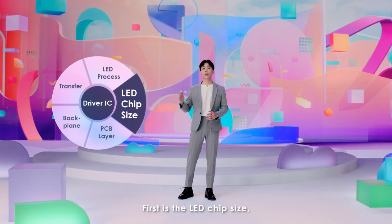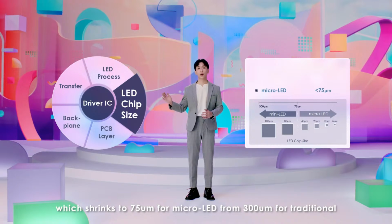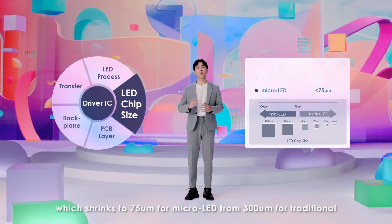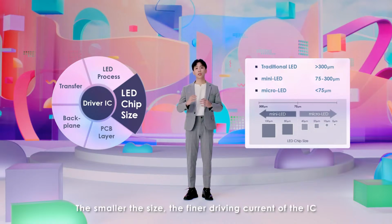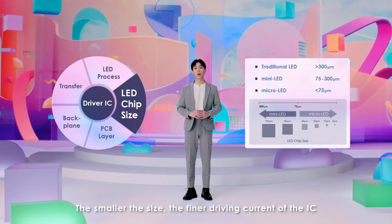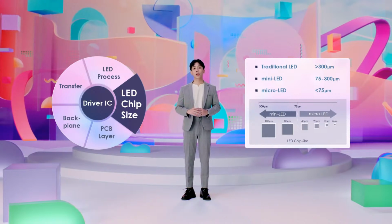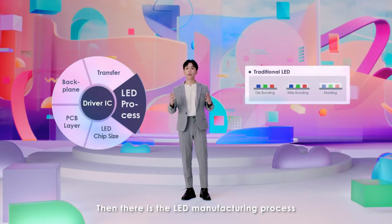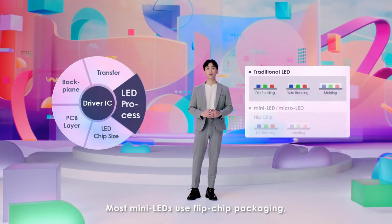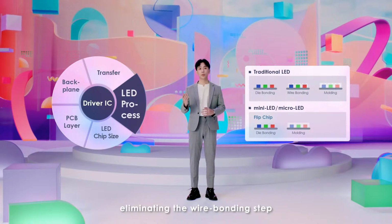First is the LED chip size, which shrinks to 75 micrometers for micro LED from 300 micrometers for traditional. The smaller the size, the finer driving current of the IC. Then there is the LED manufacturing process. Most mini LEDs use flip chip packaging, eliminating the wire bonding step.